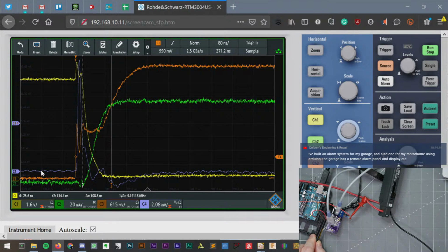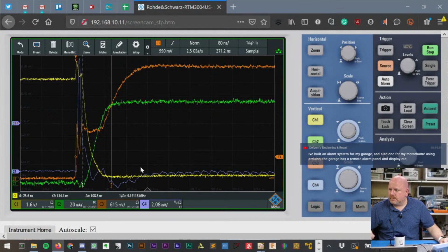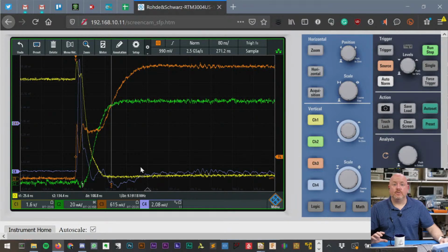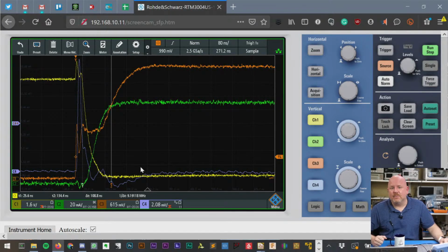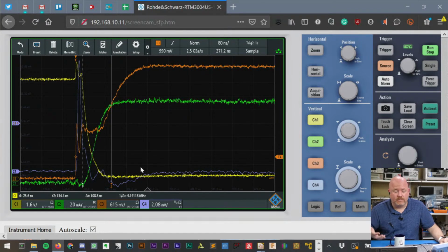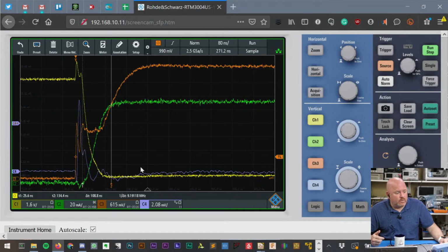When the MOSFET turns on, it is creating a huge EM field that we're picking up with the probe. Just by switching this on so fast, the probe is kicking out a huge inductive spike. I'm sorry, a huge electromagnetic spike. And so when you hear about things being EMI sensitive or having to go through EMI compliance or EMI testing, this is an example of where a MOSFET that is switching creates that EMI that we have to and want to avoid.